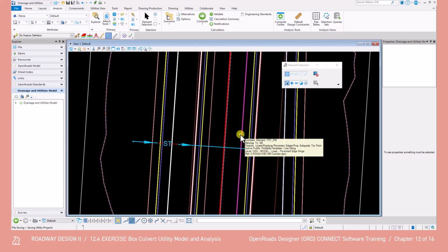So then we need to locate the applicable wing wall standard drawings for the proposed box culvert based on the structure skew and slopes of the proposed roadway at all 4 corners of the box. The wing wall standard drawings are STD 17-11 through 17-14. For this exercise, the box culvert is at a 90-degree skew to the proposed roadway, so STD 17-11 is the applicable standard drawing. The proposed roadway has 4-to-1 slopes, and the box height is 8 feet.